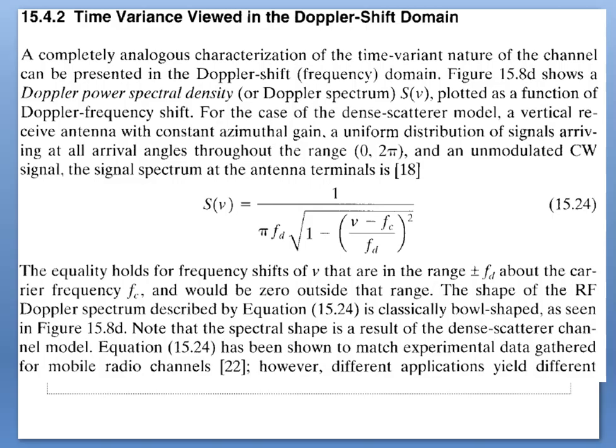equal to 100 Hz. Therefore, if this example represents a channel over which digitized speech signals are transmitted at a typical rate of 10 to the power of 4 symbols per second, the fading rate is to be considered less than the symbol rate. Under this condition, the channel would manifest slow fading effects. Note that if the abscissa were labeled in units of wavelength instead of time, the plotted fading characteristics would look the same for any radio frequency or any antenna speed.